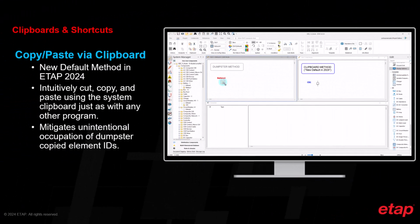Those familiar with ETAP have likely grown accustomed to the dumpster serving as an active clipboard that holds cut or copied elements. The drawback, though, is that this behavior leads to the IDs residing in the dumpster and remaining occupied unless they are purged or moved from the dumpster. To address this, an alternate copy-paste method utilizing the clipboard was added.